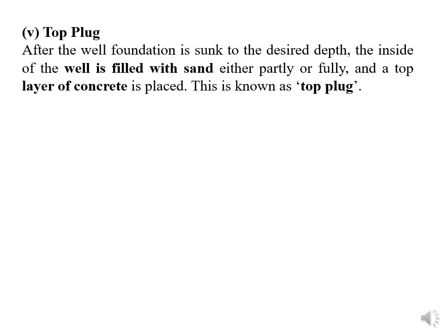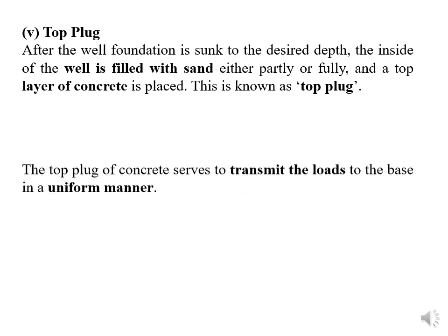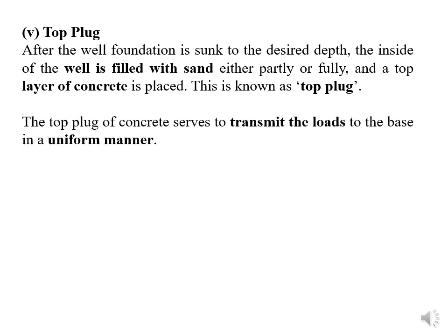Top plug: after the well foundation is sunk to the desired depth, the inside of the well is filled with sand, either partly or fully, and a top layer of concrete is placed. This is known as the top plug. Once you fill the well with sand, you can close it using the top plug. The concrete serves to transmit the loads to the base in a uniform manner.